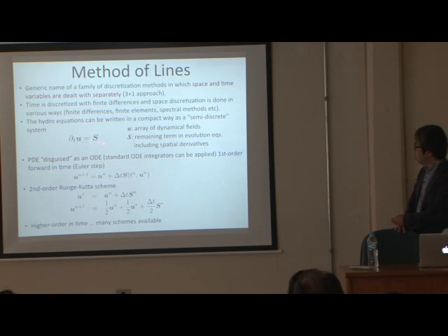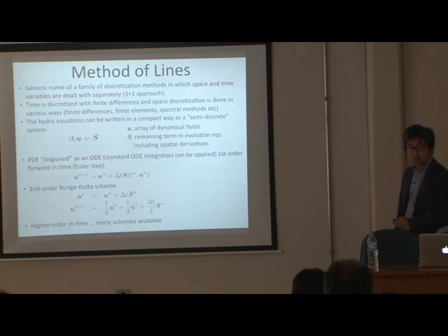S is also calculated from the previous time, including the conserved variable at the previous time. For the second order Runge-Kutta scheme, we can put one step in between to the next time step. You write u star. So we calculate the next time step using the contribution of the previous one plus this half time step part, and this flux correction part is also there.